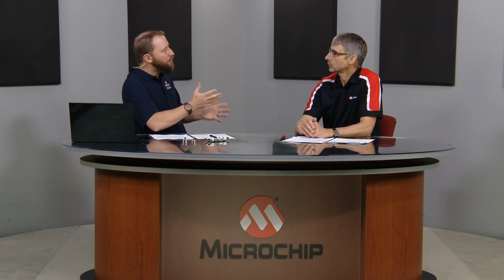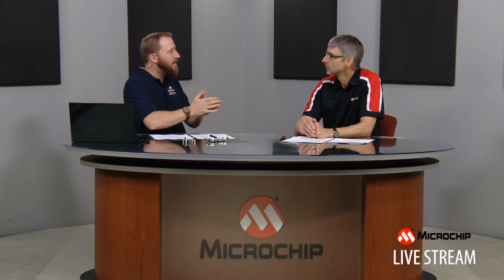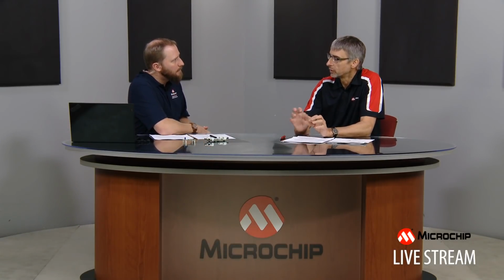Now, when we talk about drift, I was showing a drift being 130 times better. It should be pointed out as well that that's comparing a typical number for the general purpose device versus a maximum number given for the zero drift, which is pretty common, that for, say, a non-zero drift device, they don't even specify a min and max. That's correct.